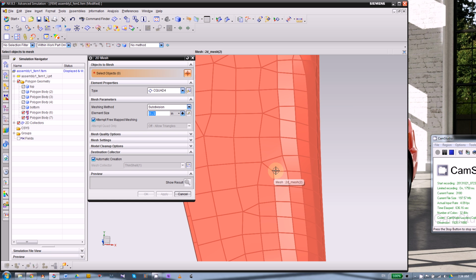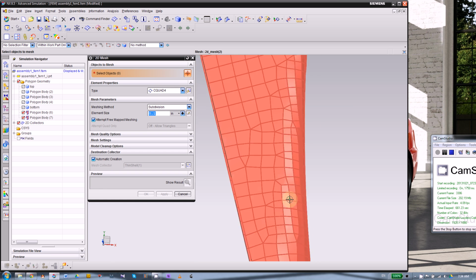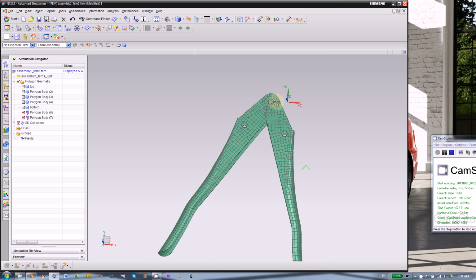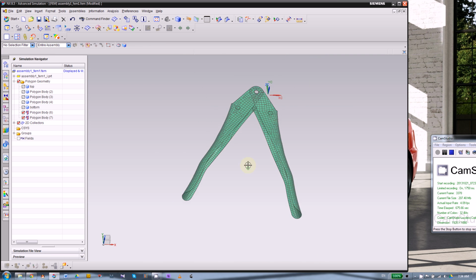As you can see, the angle here is a very big angle, and for quad 4 elements, if this angle is close to flat, it will violate the threshold, so it will not be ideal for simulation. But for our application, it's fine, and Dr. Zada said it's fine, so don't ask me about that. And that's all for the 2D mesh.